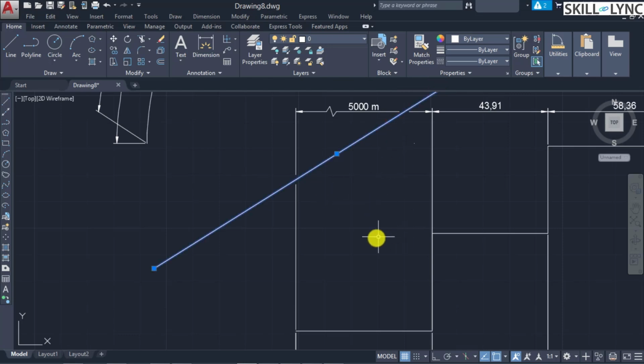So next what we have is the specification of the inspection dimension. Inspection dimensions vary from our normal dimensions by specifying how frequently the manufactured parts should be checked to ensure that the dimension value and the tolerances of the part are within range.